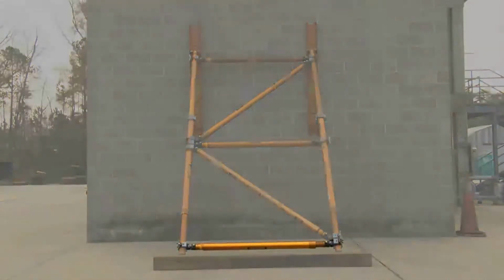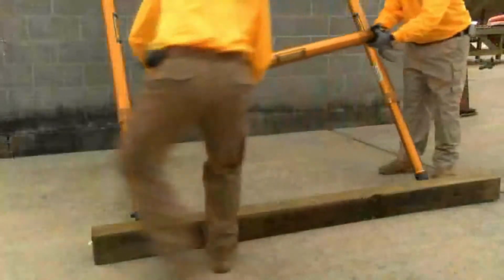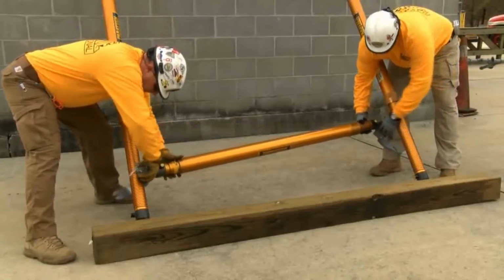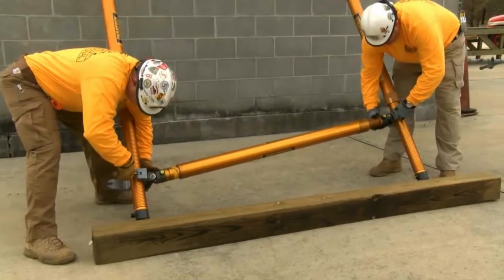Now insert the second of the lateral braces. This brace goes on the bottom, approximately a foot from ground. Notice again the non-movable side goes in first and is going on the threads. It is permissible to clamp on the threads or onto the tube. It will not damage the threads.